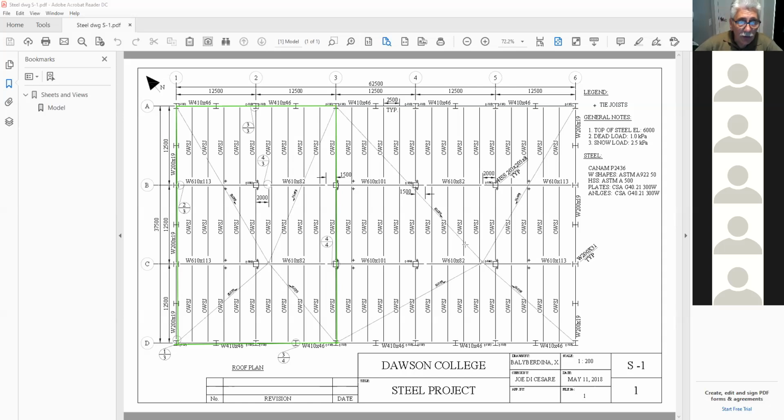For example, the easiest way to create a slope is simply by lowering a column. But horizontally on the girder, on that Gerber, how do we know where to place it? You always put it at the end of the cantilever. That's the best place to put it because the cantilever can flex. It can deflect under the load, and therefore you want to make sure the drain is there. Okay, makes sense.